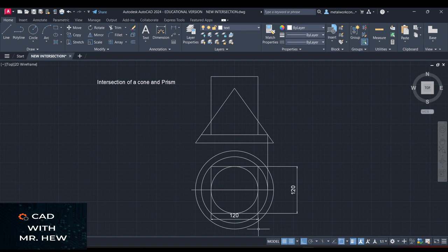To get the highest point on the prism now, can you guess what you think we're going to do? Right, we're going to do the same thing. We're going to draw this line up to intersect the side of the cone, which is represented by a triangle, okay? So we're going to go up, which should be the same point there. Enter. I'm just showing you with the same point. Then you're going to go at the intersection, go across. It should be a horizontal line, okay? Enter. All right. Now, this is the highest point. This is the lowest point. So let me mark them for you.